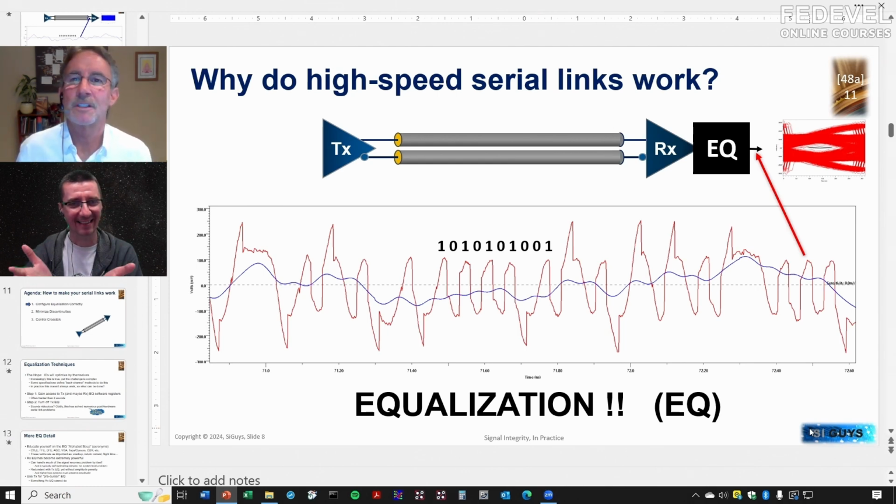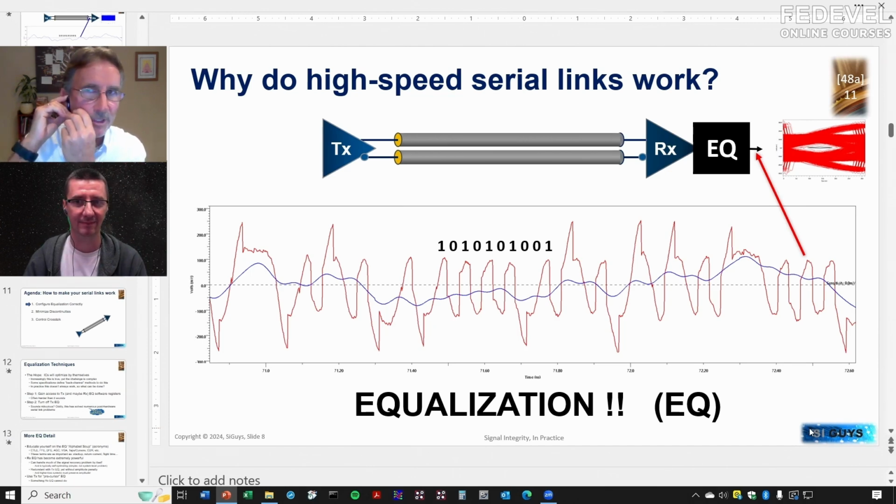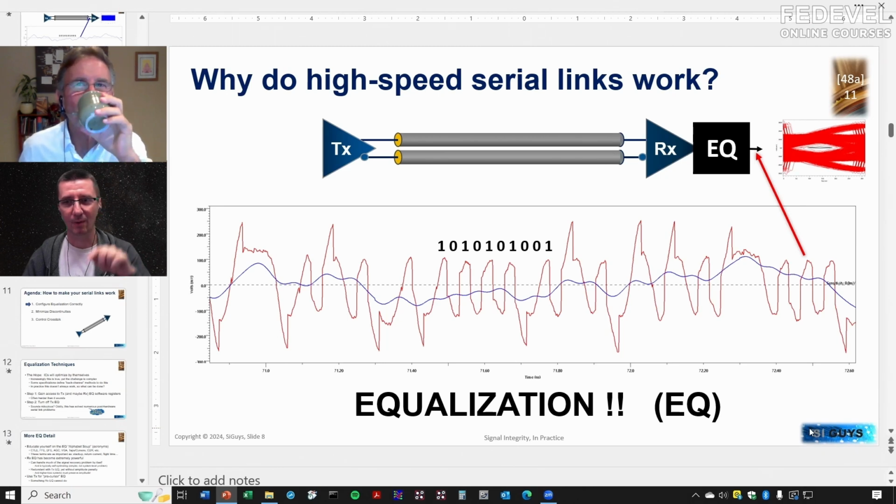I was exactly thinking about this because, again, we may need to explain PAM4. It means there are 4 different levels, correct? Yes, encoded, but I don't have a slide on that right here, but Google PAM4. So it's not going to be only 0 and 1, but there are 4 different levels, and there will be real signals with 4 different levels, and this equalization has to recognize which one it is.